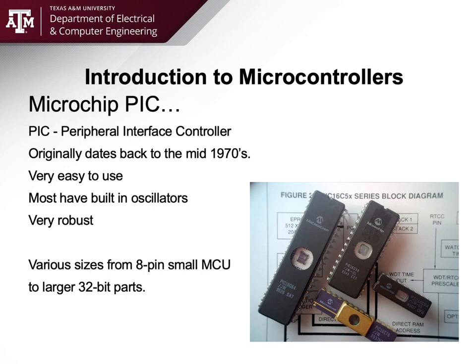Most of the ones I've used, just recently used one actually, it had an ADC converter built into it, had SPI bus built into it. I was able to read an ADC converter, determine a value of a potentiometer, and actually write some code to do some mathematics on that, and output a waveform going upstream to a PLC being used in another application. So 8-pin microcontrollers are actually very common.